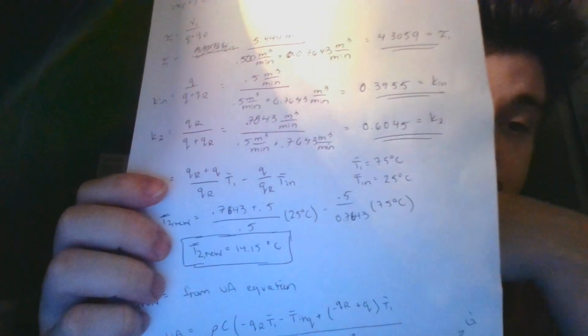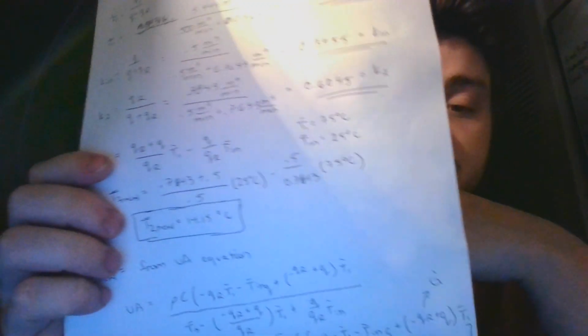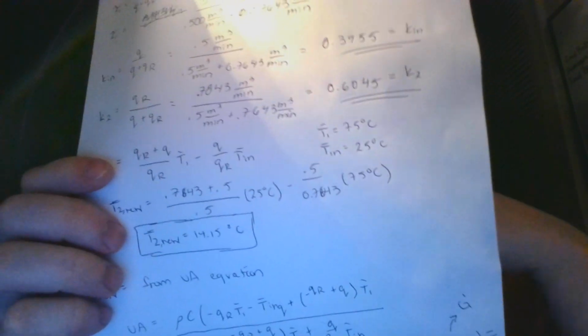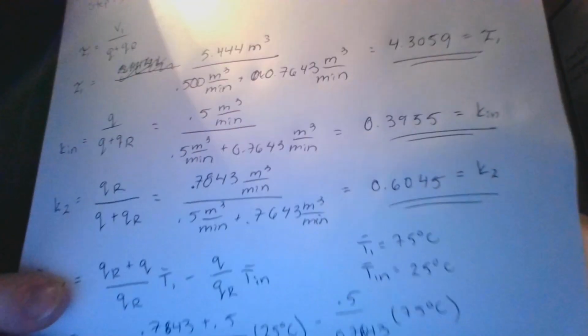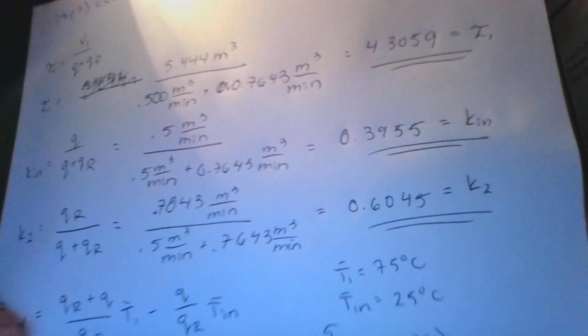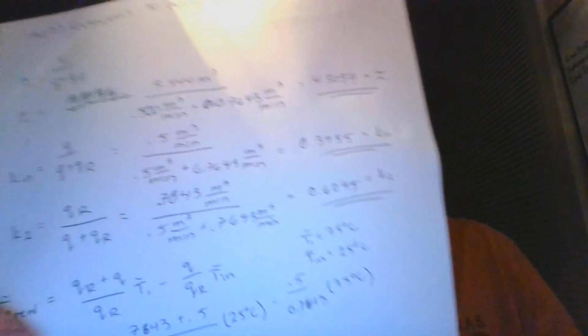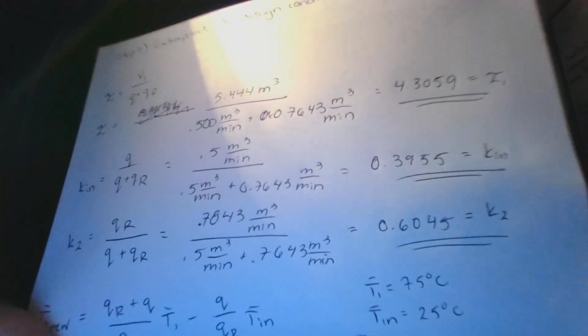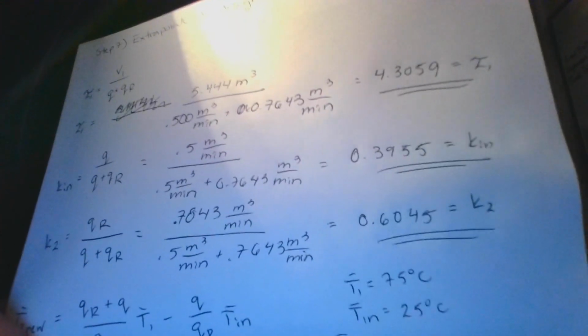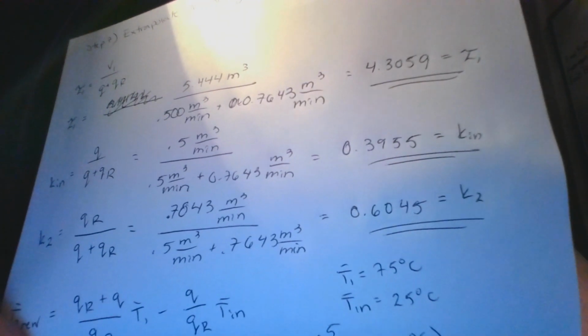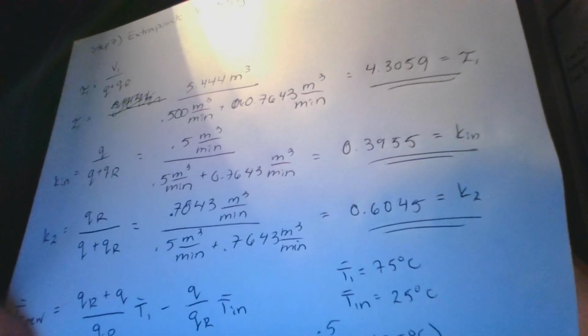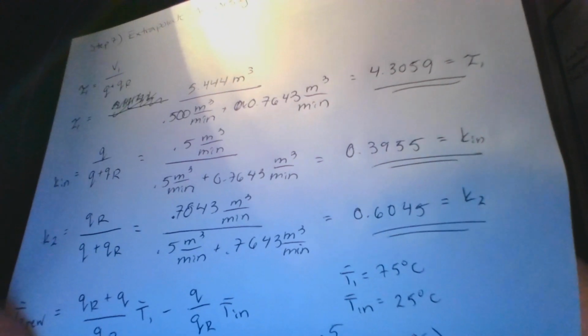Now, the Simulink model that I have for my executive summary is lacking oscillatory motion. I think this is due to the zeta value that I have found for my system, which can be found in my Excel document, but it is around 3.4. And with this zeta value, we are going to see an overdamped response, which does not give us oscillatory motion. And the maximum temperature differential that was seen from my temperature change inside of the process was 10 degrees Celsius. Thank you.